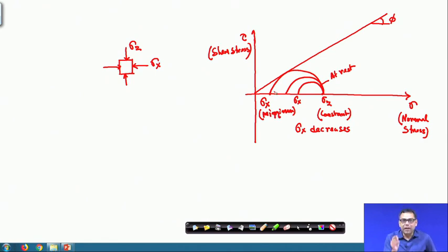We cannot get less than that, because this Mohr circle has already touched the Mohr Coulomb failure envelope. As I have already mentioned, any Mohr circle will not cross this line. So, this is the lowest sigma x value. For the active case, sigma z is equal to sigma 1 and sigma x is equal to sigma 3.